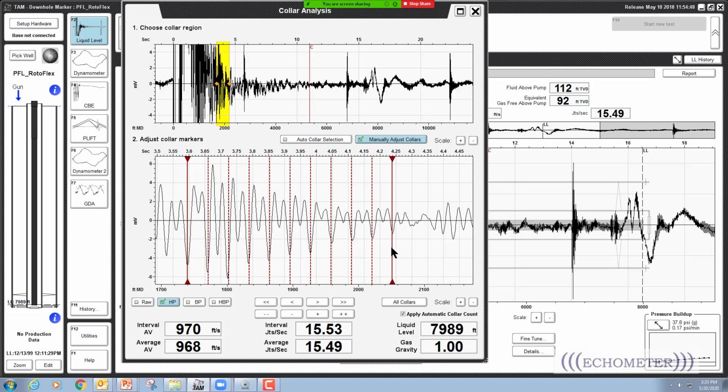Okay, so about 25 years ago, I did something like that. We shot fluid levels on 55 different wells, and we took gas samples on the casing gas. So you have to specifically sample the casing gas if you're going to shoot the fluid level and not use the gas from the plant or the gas from the separator. We did that. And as long as the percent CO2 was less than about 30% CO2, then the hydrocarbon gas gravities, it might be a 0.83, and the gas analysis would be like a 0.81. Usually within 2%. 2% or so was a typical error when the CO2 percent is less than 30%, because the acoustic velocity is a measured value. We have a correlating algorithm inside the software that calculates the relationship. So I guess that's my answer.